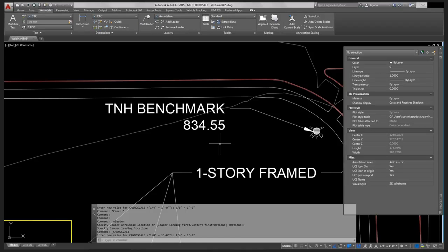Surveyors went out, and the whole site was off by, in my example, only 2/10, but in their case about 2 feet, which made a huge difference. Luckily, they raised their surface and all their points up the difference, and it was caught before it made it out the door.